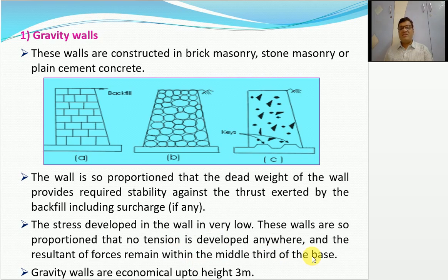Since we don't provide any reinforcement in this one, obviously the stress must be very less. Accordingly, you have to increase the dimensions of the gravity walls, and these walls are economical up to a height of 3 meters.